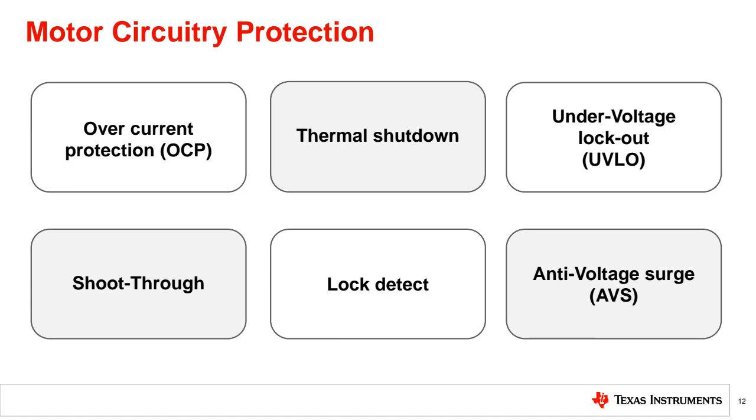If your motor demands more than 10 ampere, overcurrent protection will generate a signal. You can stop your circuit and motor. This is called overcurrent protection. You need to detect DC bus current, also phase currents.